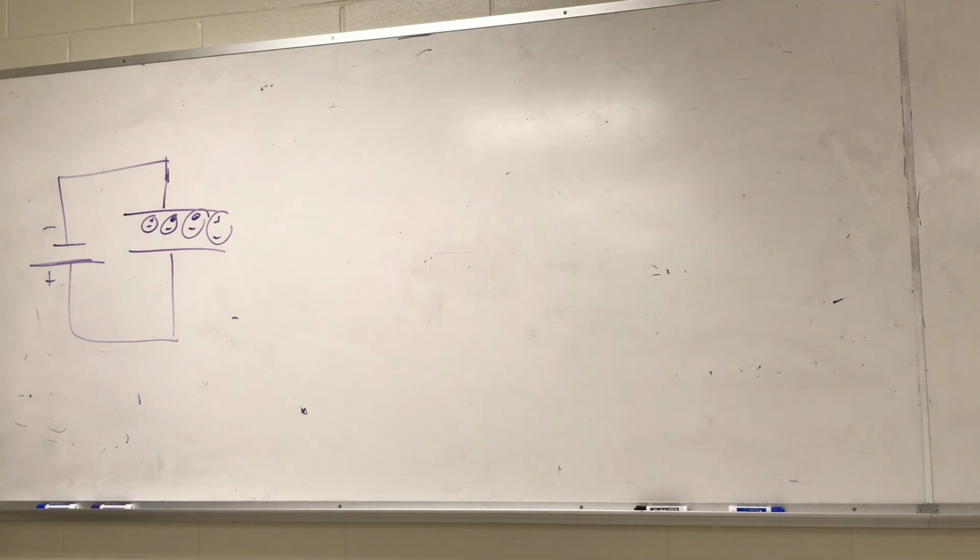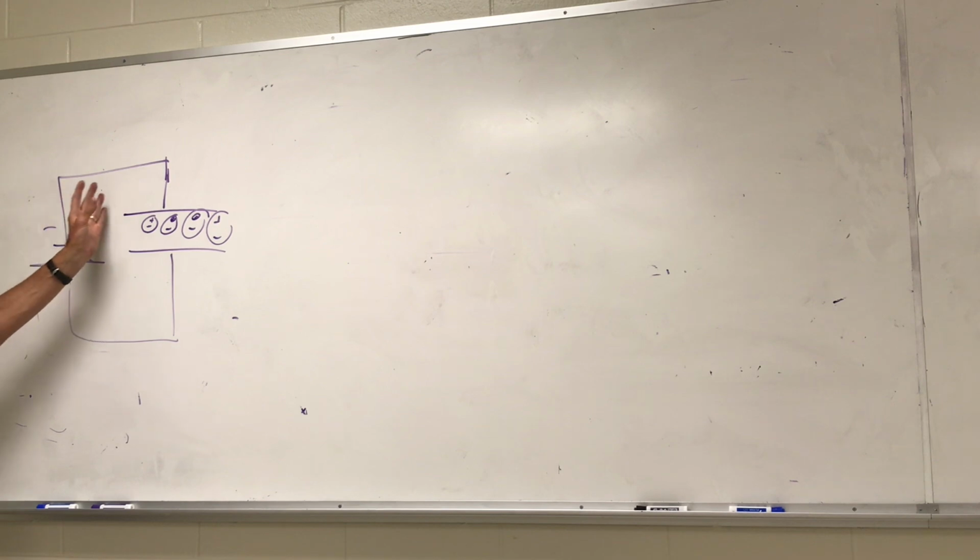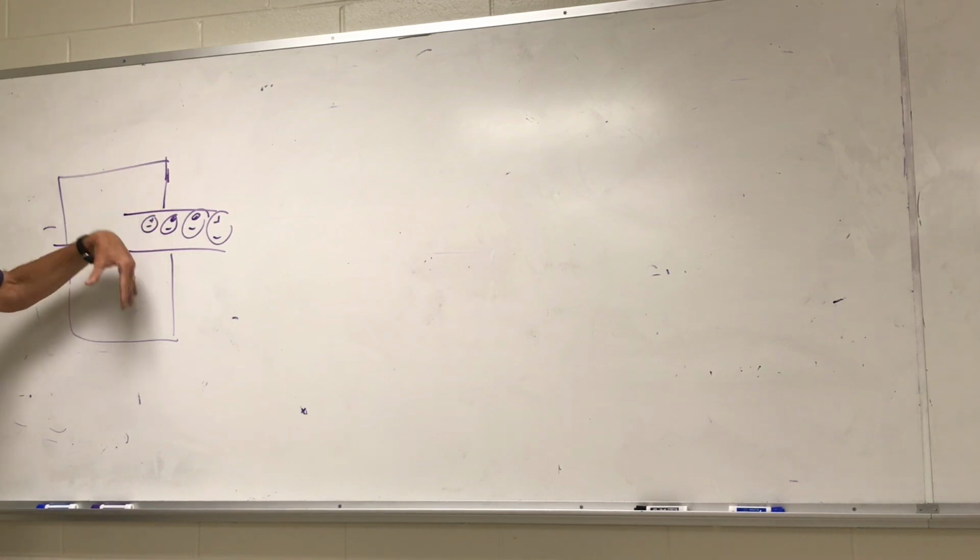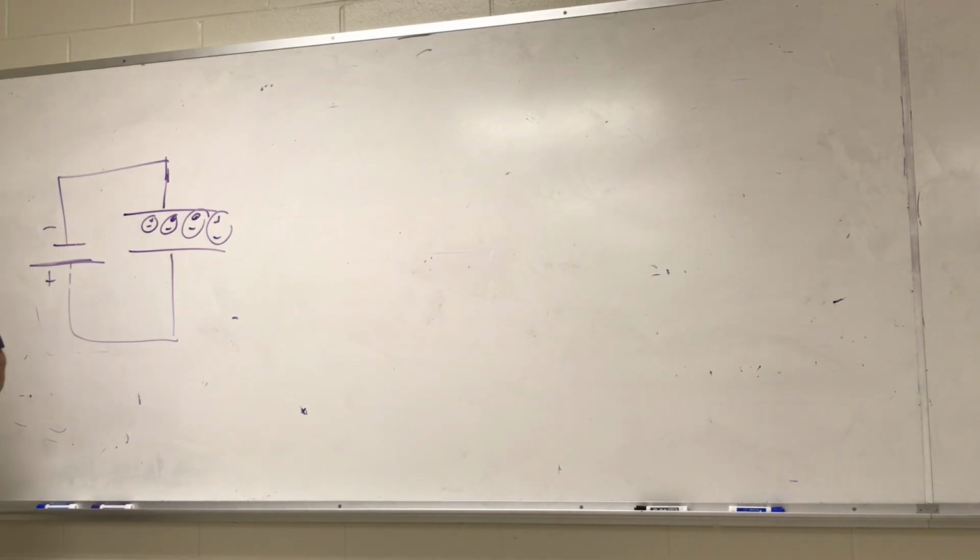Now what happens is, if you have an electrolytic capacitor and you have a DC voltage, you can have a DC voltage with noise, with some sort of an AC superimposed on it. As long as the polarity doesn't change, these dipoles will always be oriented in a certain order, either up or down. But the minute you get something where the dipoles will try to flip, now it starts heating and these things blow up. And I had an experience with them. I wasn't there when it blew up, but I saw the aftermath.